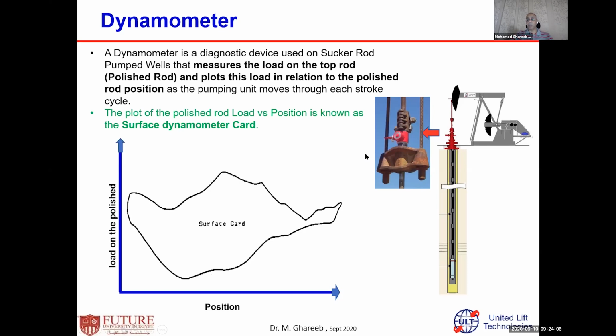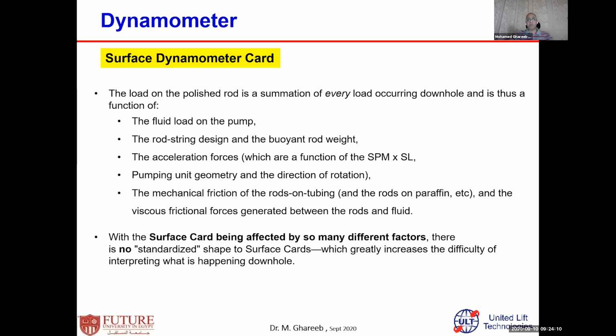But my pump is running downhole, okay? The surface dynamometer card just simulates the load at the surface. This is what you call the surface dynamometer card. And for downhole conditions, it's not easy to simulate only the downhole pump with the surface dynamometer card.